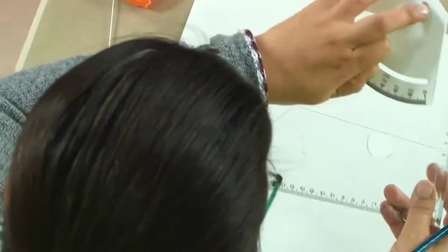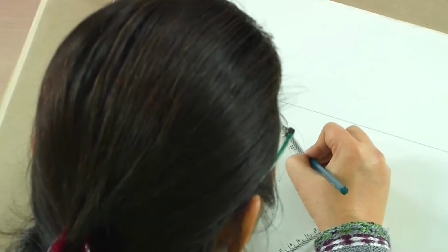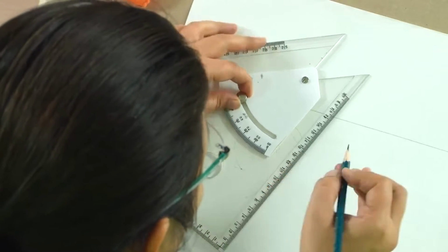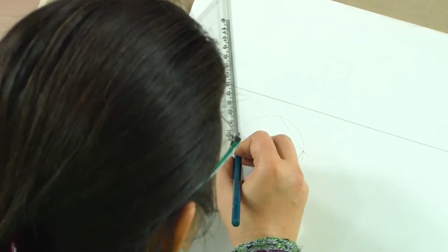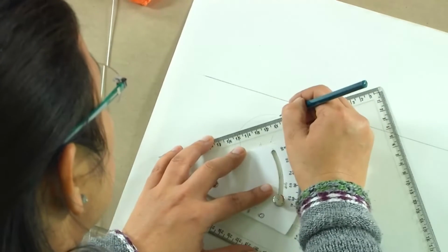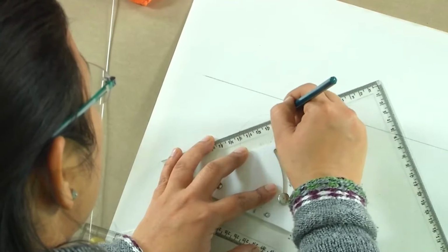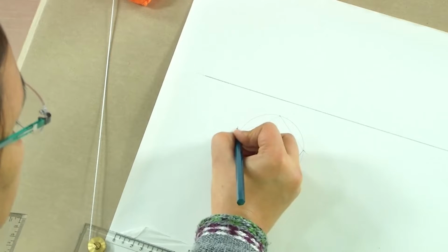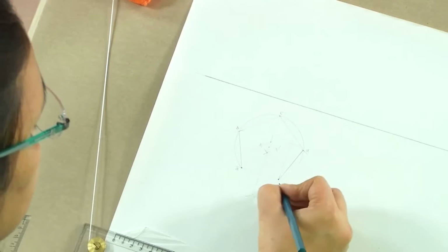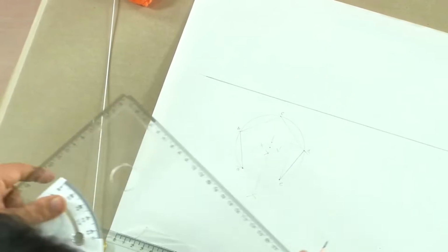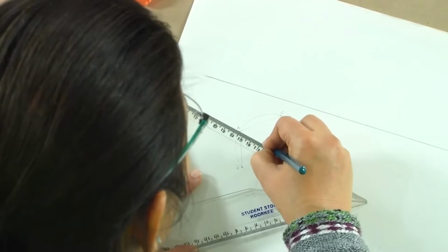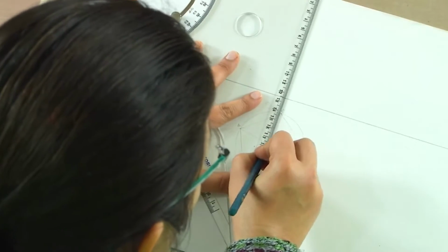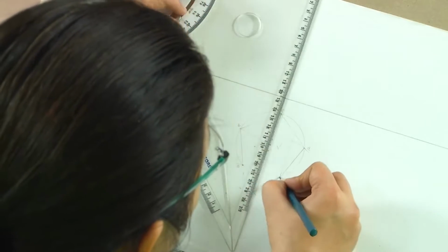So, this is our pentagon, and here one of the sides we have assumed to be kept parallel to the VP. This is the regular pentagonal base of the pyramid in question. Now, let us number them: A, B, C, D and E, and this is the apex O. Since it is a pyramid and it is kept on HP, we will be seeing these edges connecting the apex to the points in the base.